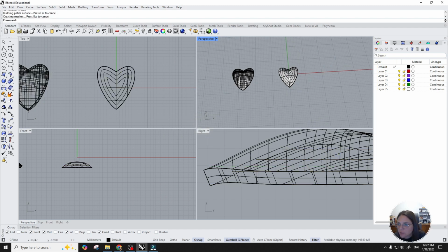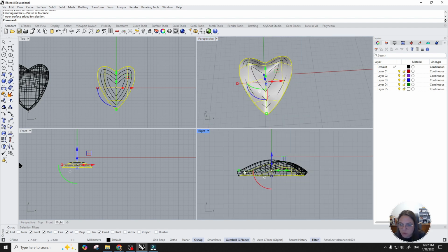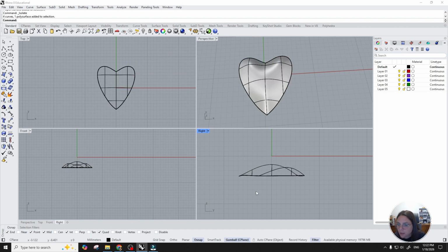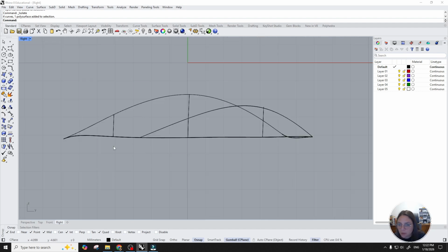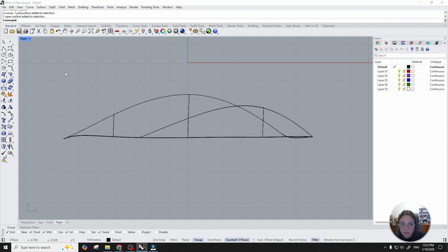Another option is to choose the patch. And let's say, for example, okay, this is the patch. One more trick here. I want to see just this one because here it's super hard to work. Here I can hit isolate object. And I want to cap the object. Now the thing is that the command cap only works with 90 degrees, and here I don't have 90 degrees for the surface.